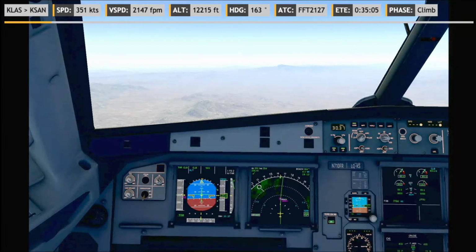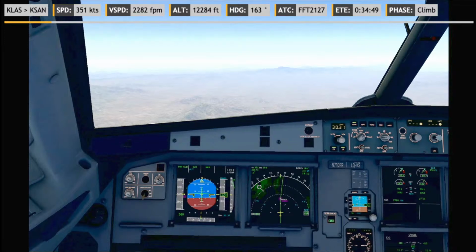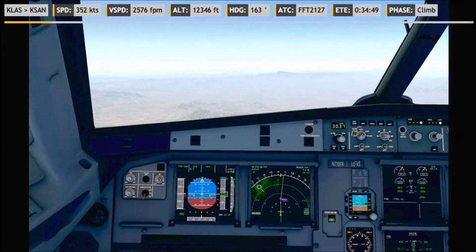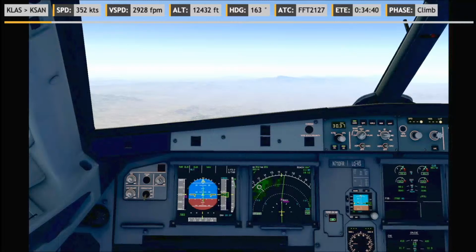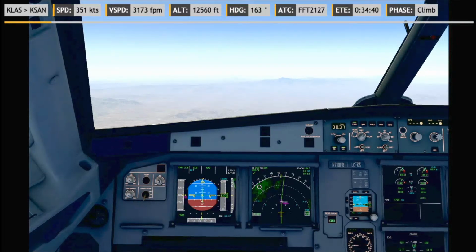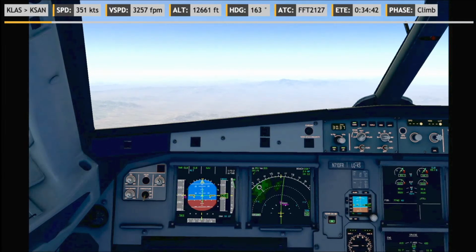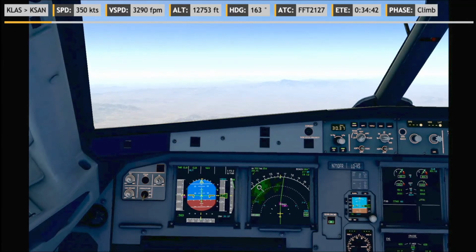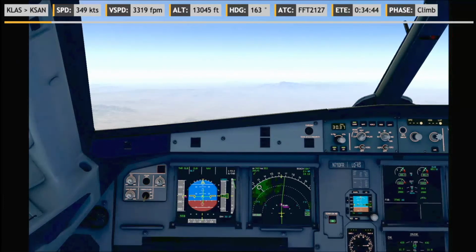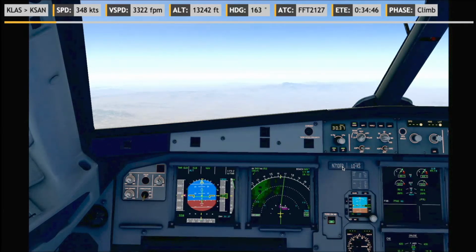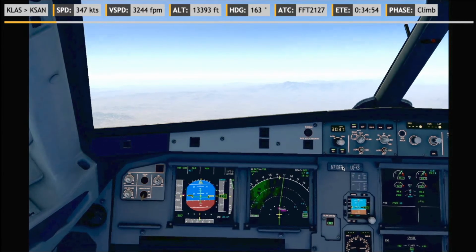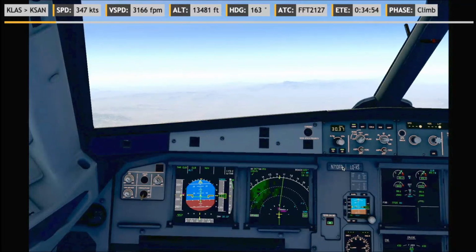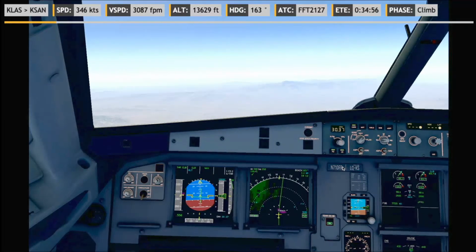Because if we go faster, air over the wings is accelerated. The air over the wings is going faster than the airplane itself. So it might be that if the airplane goes under the speed of sound, the air over the wings would break the sound barrier, and you would have all sorts of strange aerodynamic effects. That's why we have a maximum Mach number that the airplane is certified for, which we don't ever want to exceed, because you start breaking stuff.